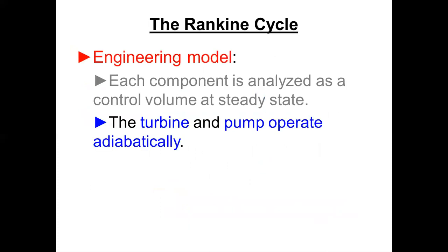The turbine and pump operate adiabatically, and that's a fancy word for what? They have no heat transfer. So adiabatic means we're just not losing any heat from the surfaces of these things to the environment. In reality, we are, but they're really pretty small terms. There's not much of an error involved in ignoring the heat transfer from a turbine or a pump.